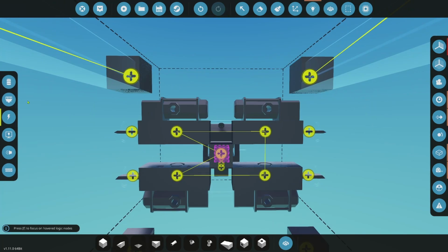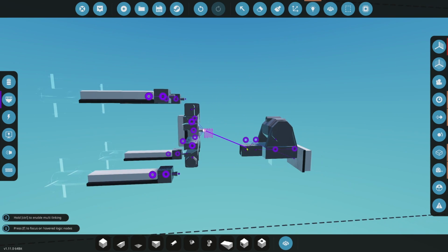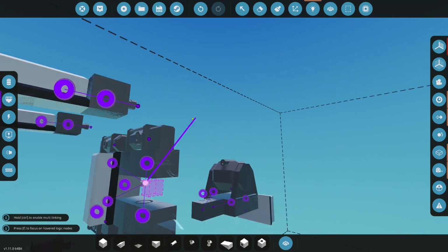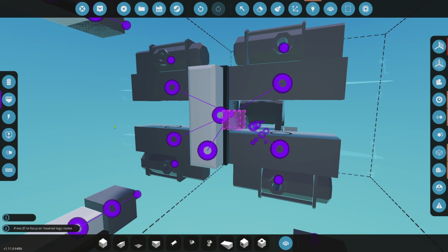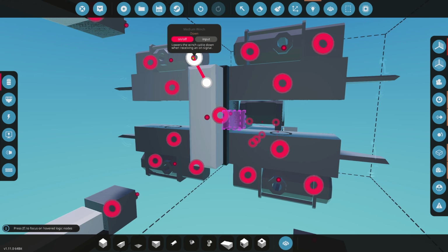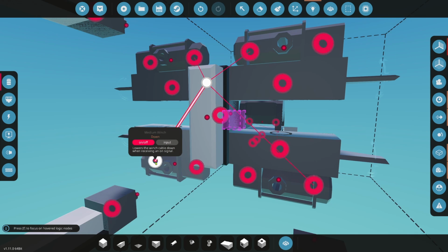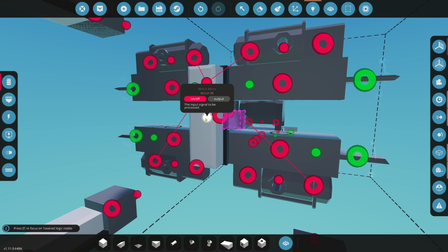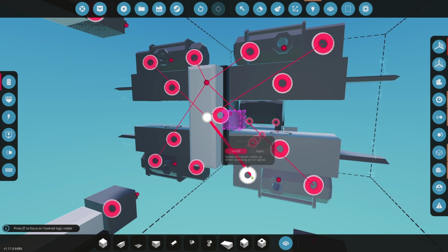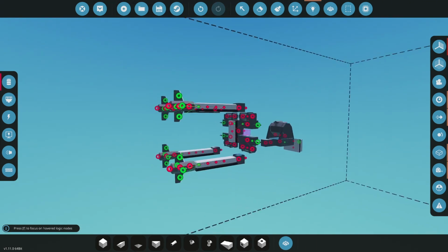Next, we want to grab the composite node. So we're going to go from the cable anchor. Again, it's sending the information from the panel out through the large winch, through the cable, into here. Then we send it into the box here, where it converts it from composite into the Boolean. Winch out is going to be down, down, down, down, and then we have winch in, which would be up, up, up, and up. All right, good. So that is all set up.